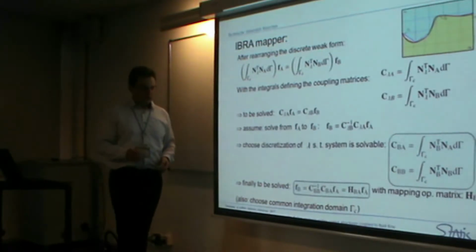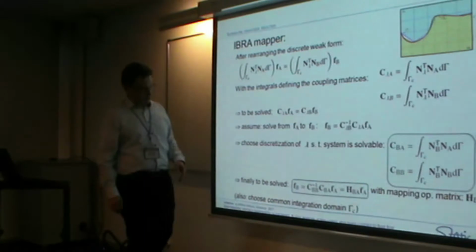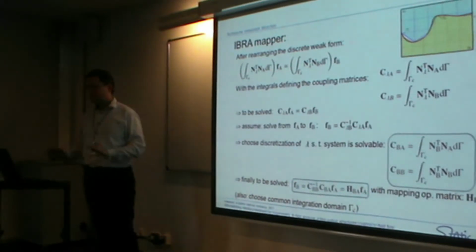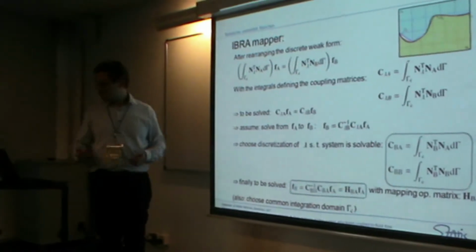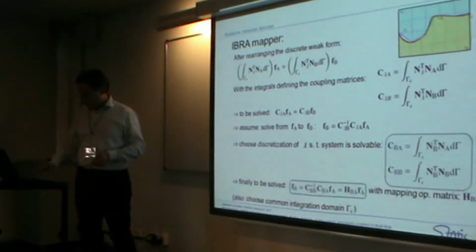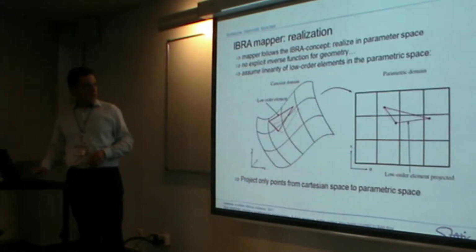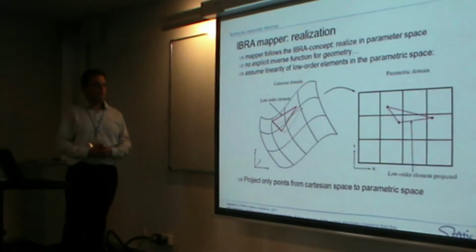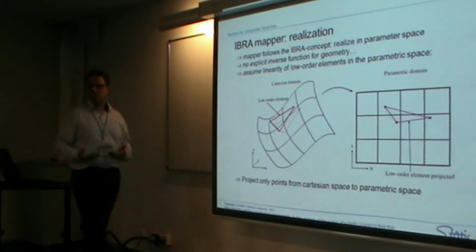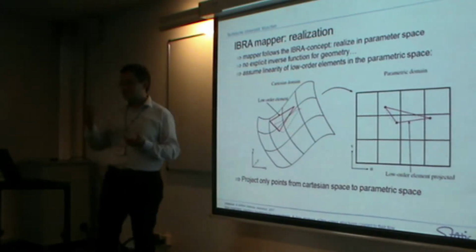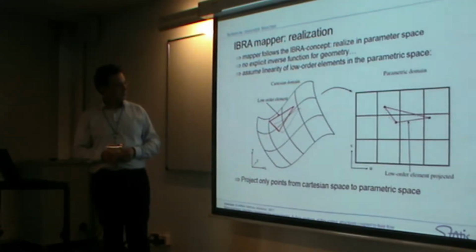It works very nicely. Just a comment, this would be 2 more slides. The choice of the common integration domain. At this point we are going for the exact geometry for the structure, which is described by the NURBS patches, which are coupled and trimmed. And then it boils down to a lot of additional questions which we did not see before, as we went for low order elements, coupling what we did already some years ago with the colleagues here also in Barcelona.